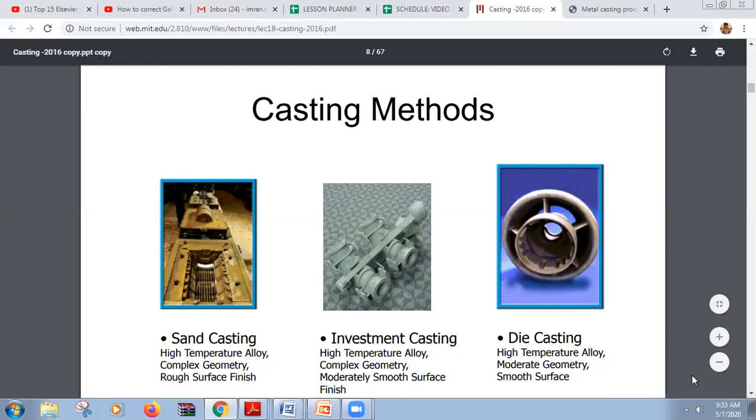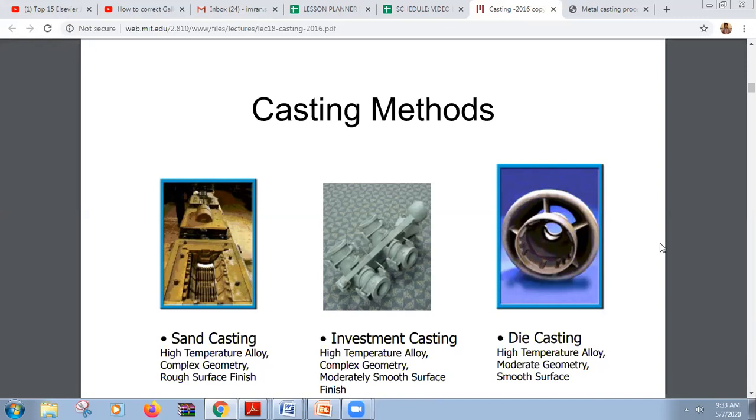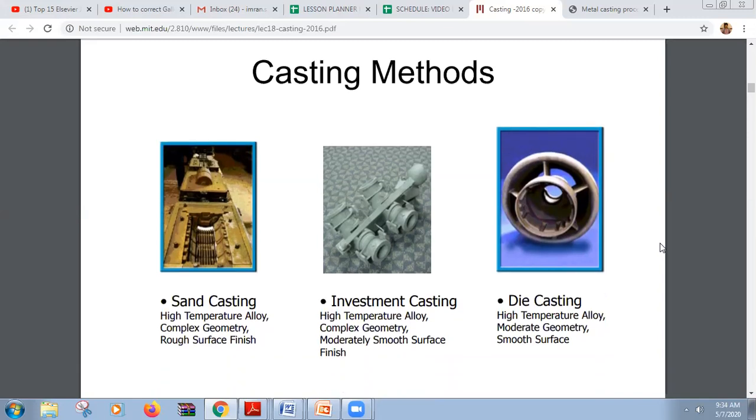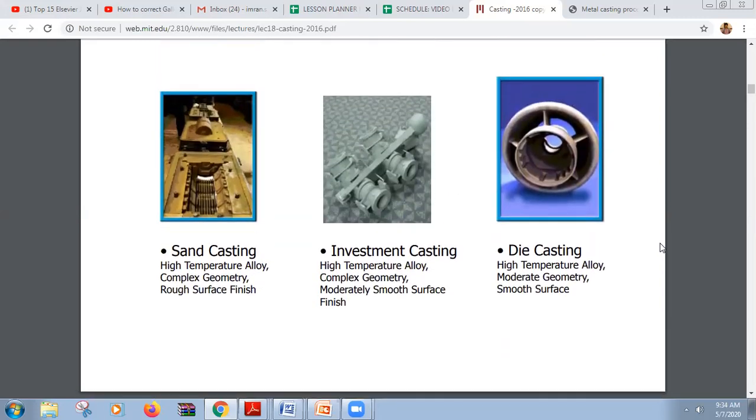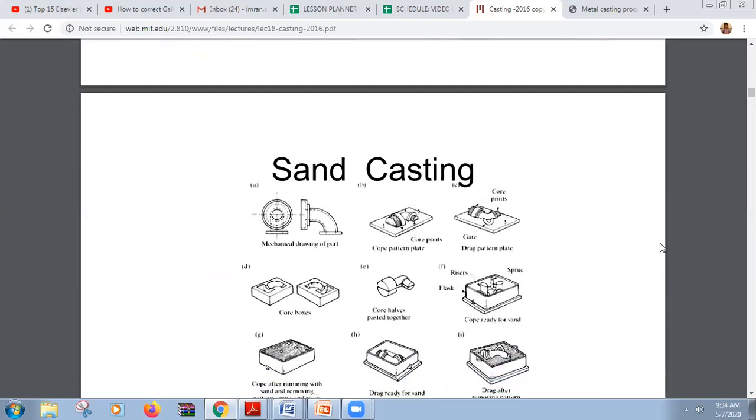In this process, pressure or force is not applied except in one case. One case is exceptional, that is known as pressure die casting. Otherwise, pressure is not applied at all. In this process, only temperature is applied, and that too above melting temperature. So casting is a process that basically uses heat, except for one exception, and that is pressure die casting. Otherwise, all the other casting processes are limited to heat only.